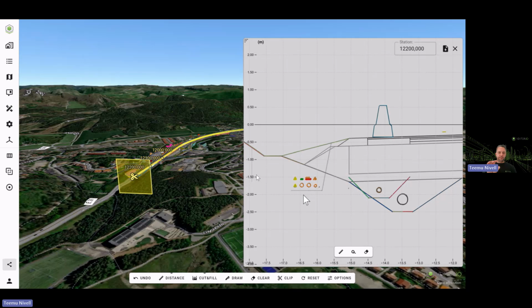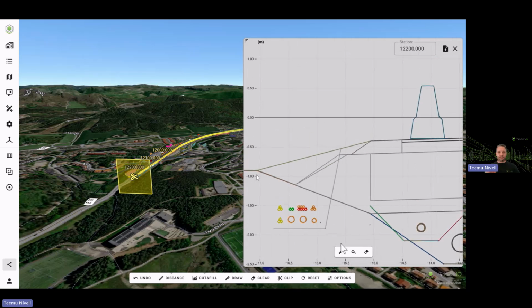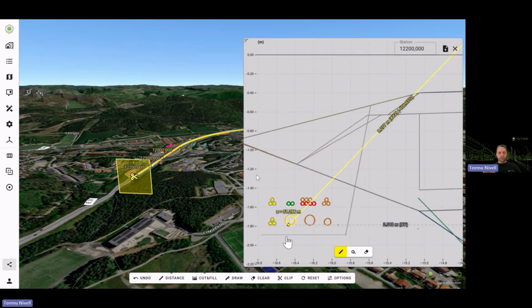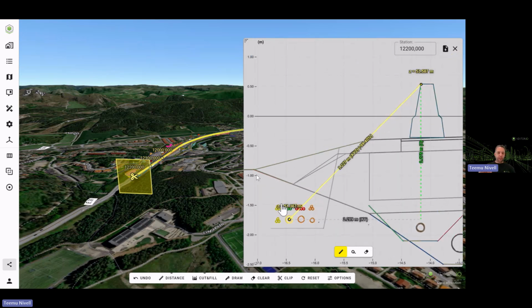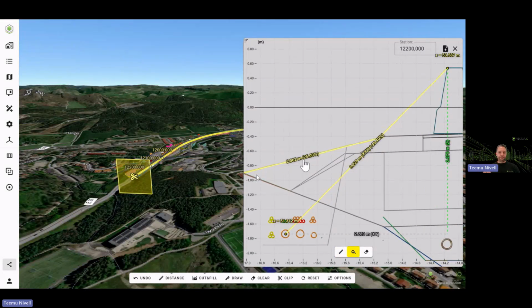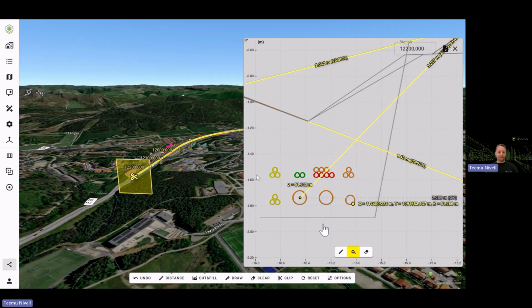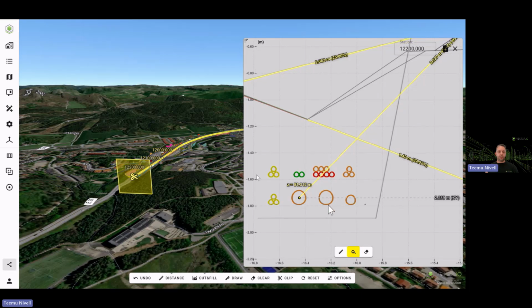So then we can zoom into details, for example, some pipes or manholes, and you can snap in any object here. It's good to note that you can snap even in the center point of your IFC object. You can get the slope information automatically. And as I already said, everything you do here, you're adding the measurements, anything, you can share these results with other users. So you can add the coordinates points.